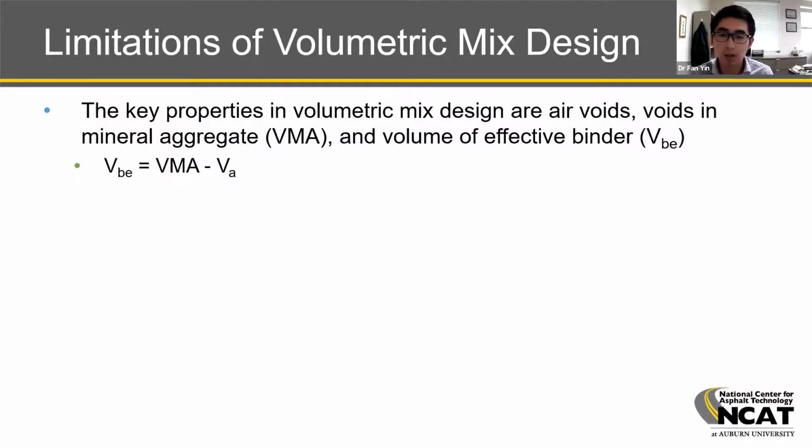What are the limitations of those volumetric mix designs? Well, if we go back to look at the volumetric design methodology, the two key parameters in those design approaches are the air voids, VMA, which means the voids in mineral aggregate, and the volume of effective binder, VBE. VBE is just the difference between the VMA and air voids.